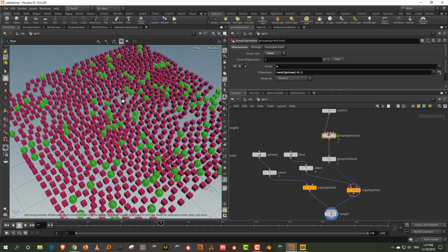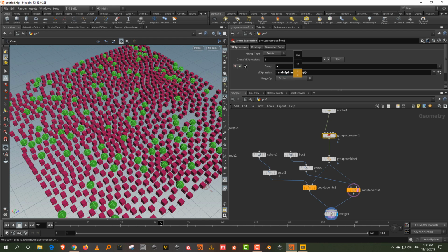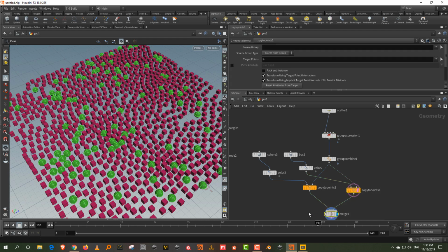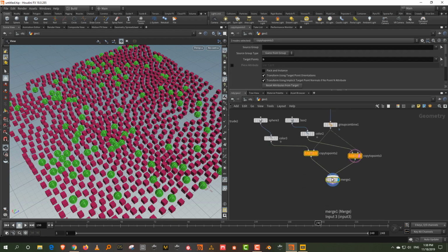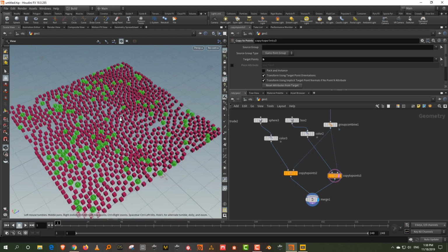And what if you want to change the selection? You just take the ptnum and add a value to it. That becomes like, if you're doing a math expression and you have an x in there, every time you change the value of x you get a different result. So when you add something to ptnum, that becomes like an x. Whatever change I make over there, if I keep changing it, you'll keep getting a different result. So this is one way of doing this, and this is how you can use the random function to select, or to make groups as well.